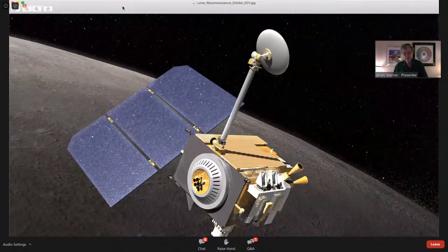This goes round the moon. It takes a couple of hours to go round the moon. It's usually roughly 1 hour in sunlight, 1 hour in shadow. And they've designed it to be big enough so that it doesn't cool down that much in the 1 hour in shadow, doesn't heat up that much in the 1 hour in sunlight. And it's got some batteries, so if it cools down when it's in shadow, it can turn on the heaters. And it's designed for 1 hour, 1 hour. Okay, that's cool. Except when we have lunar eclipses, which can last for like 3 or 4 hours. It's designed so that it barely makes it, even if they pull every trick they can.